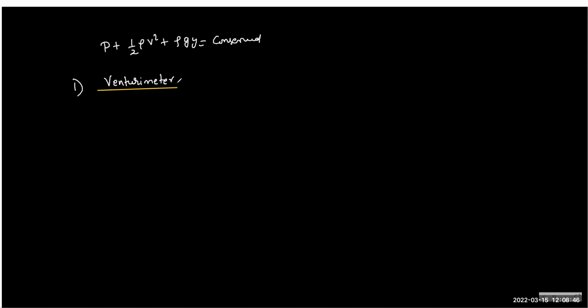So what we do is we have some location with an opening and closing door. You can open a small hole, insert this Venturi meter, and get to know the flow rate. It's pretty easy. These are glass tubes basically.